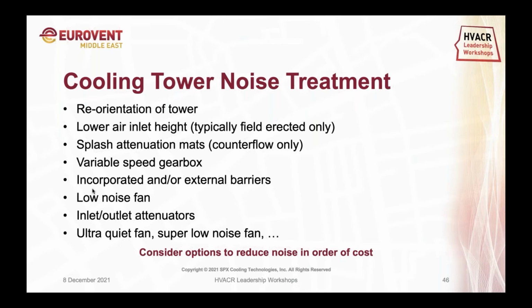Inlet outlet attenuators. Whenever you are going to use this solution, you need to consult your cooling tower supplier. Inlet outlet attenuators can create a static pressure, can change the airflow, or can create a pressure on the discharge fan, which can disturb the operation of the cooling tower. So make sure you consult your cooling tower supplier before installing any inlet outlet attenuators.